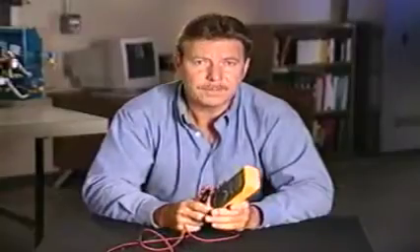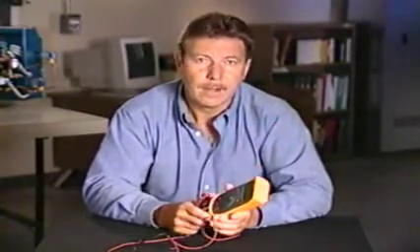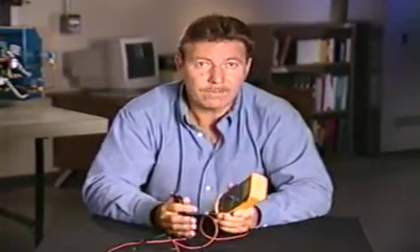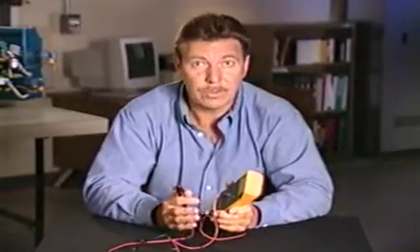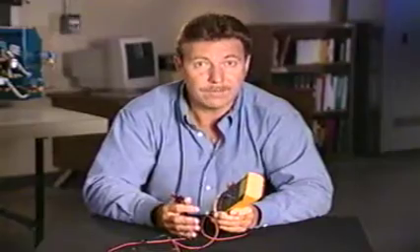This type of system can easily be identified with the help of a voltmeter. A voltage reading of 277 volts from a hot leg to ground, or a reading of 480 volts between two hot legs will identify this system as a 277, 480 volt system.